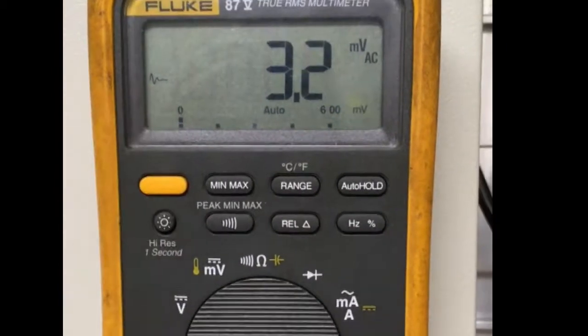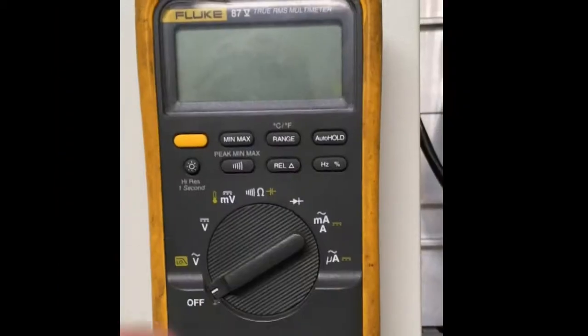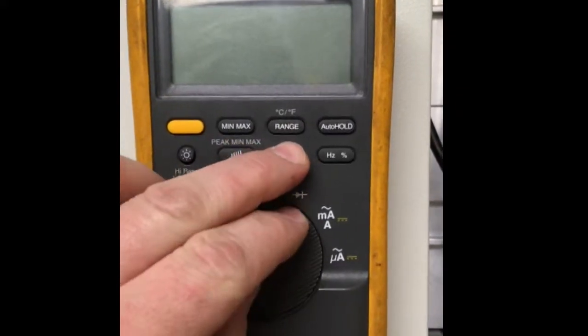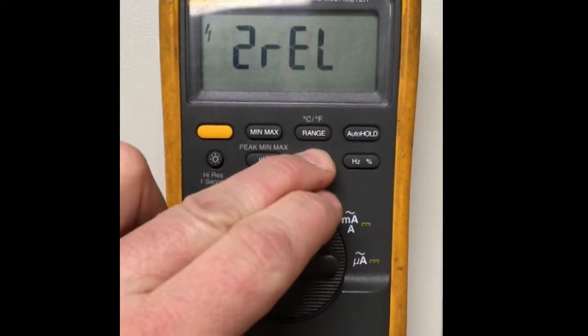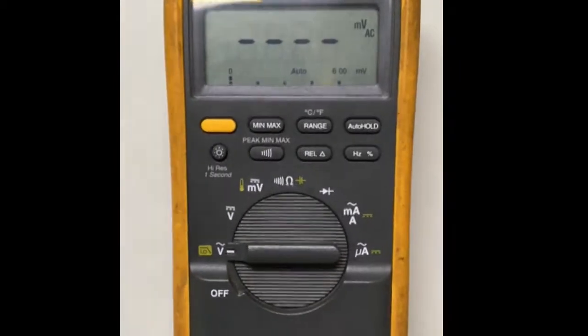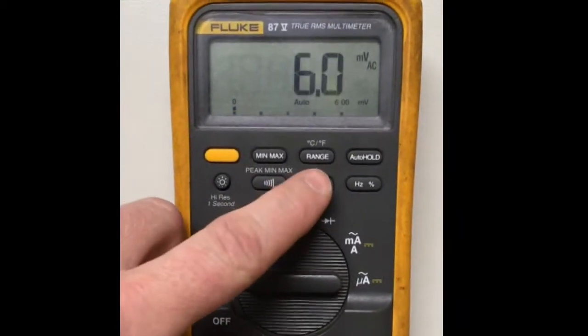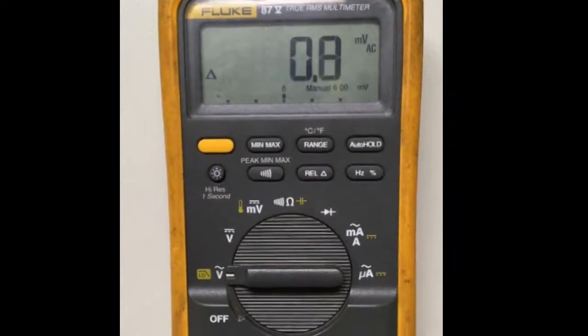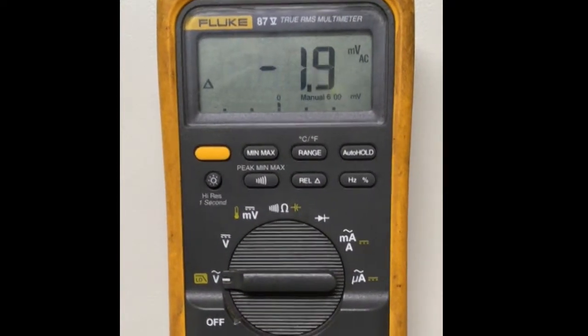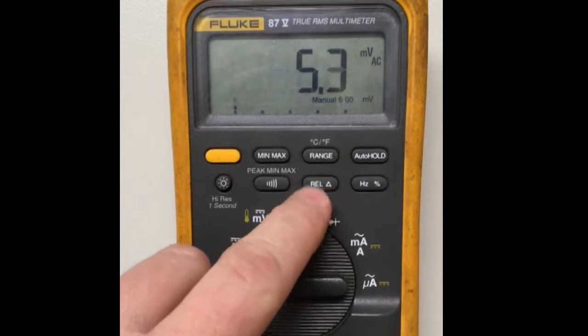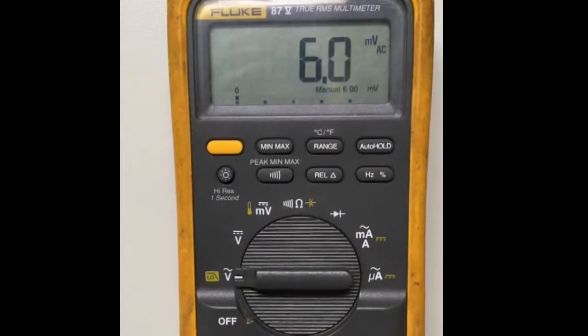The analog bar on the bottom of the screen normally represents the current measurement on a 0 to span scale. Holding the REL button during startup will allow the bar graph to represent both negative and positive measurements during relative measurement mode only. The last power-up feature we are going to discuss is the high impedance mode.